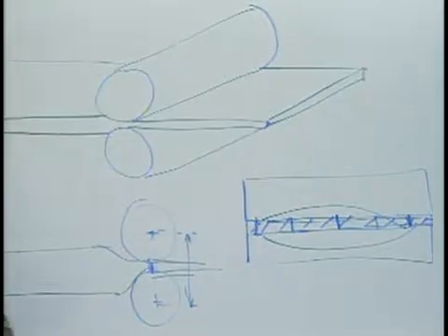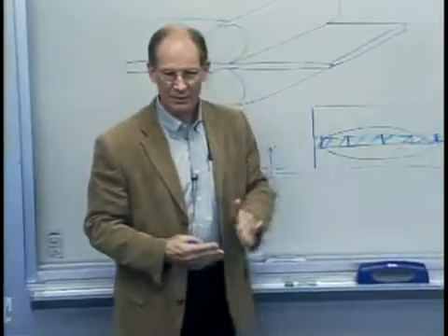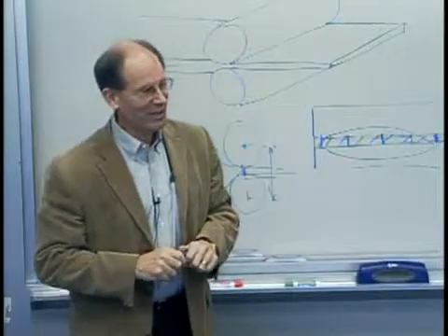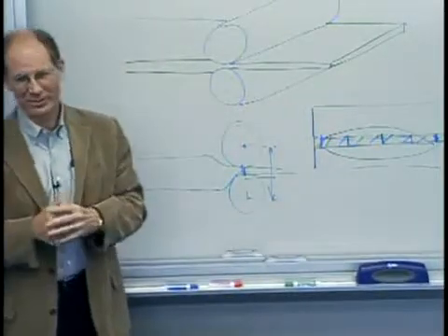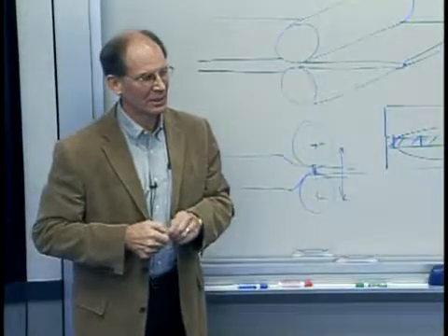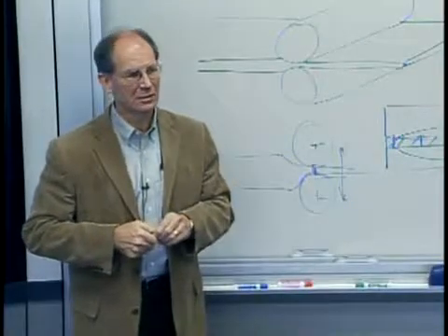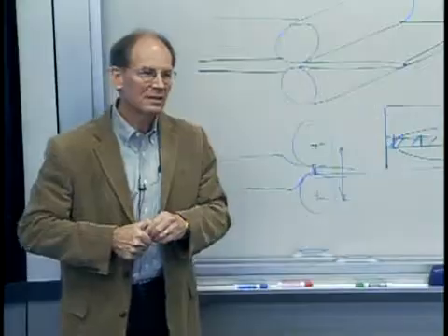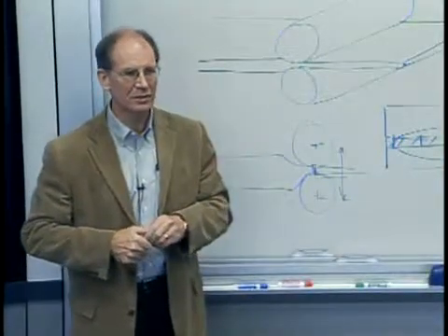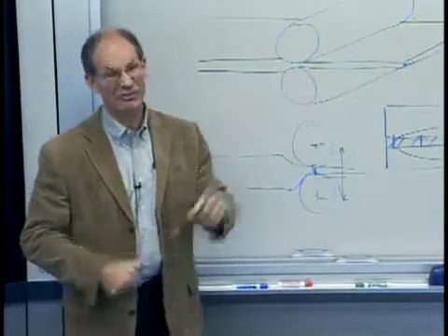Yes, you would change the rolls, and in fact what they do is they build rolls with a little bit of camber in them, because you know the center is going to deflect up a little bit, so you put some camber into it. Believe it or not, at Alcoa, that's still not good enough. This stuff is very precise. I think I shouldn't quote the tolerances, but it's on the order of, in my newly converted SI brain, I think could be 15 microns. It could be in the several 10,000ths of an inch in terms of thickness tolerance. It's not very thick stuff to begin with.